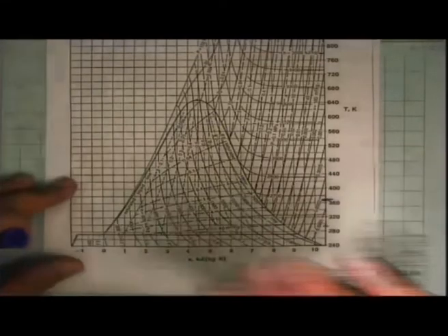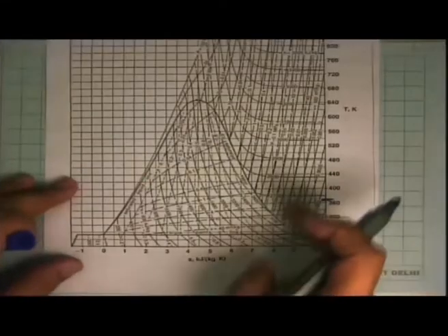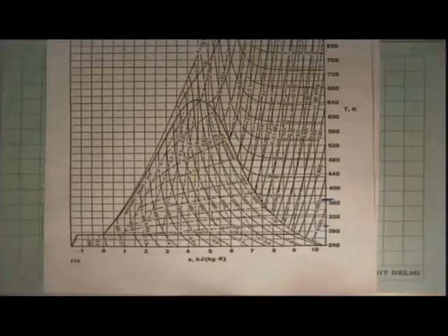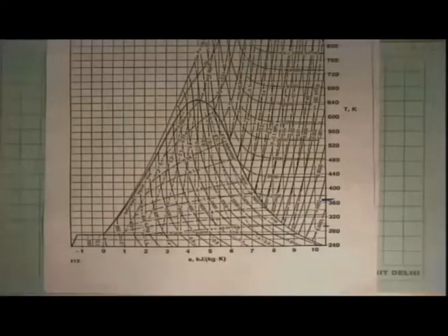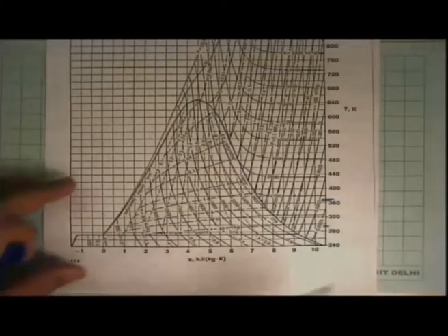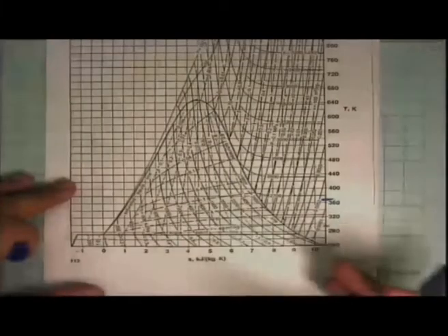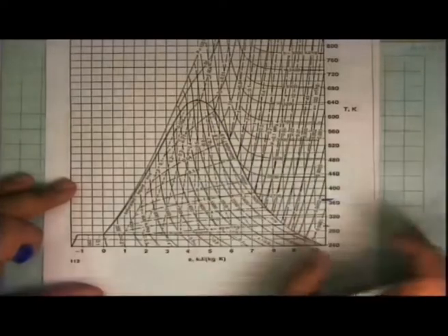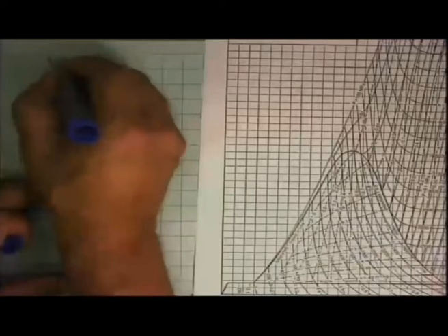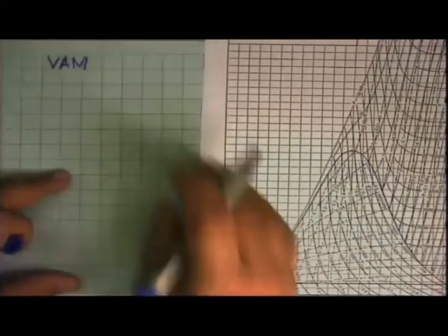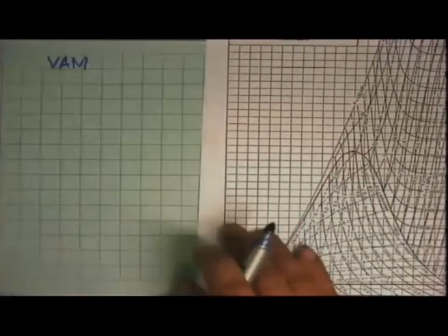And to get any reasonable amount of cooling effect, this whole system will become very huge, very bulky, and so you'll have to make a compromise and say, look, only if I can make a compromise and use all of this in a very compact way, then I will use water as a refrigerant. But otherwise, water as a refrigerant is in fact not possible for freezing at all. I can only use it at best for air conditioning, and that is the central idea of what is called a vapor absorption chiller or a vapor absorption machine, where water is the working substance.